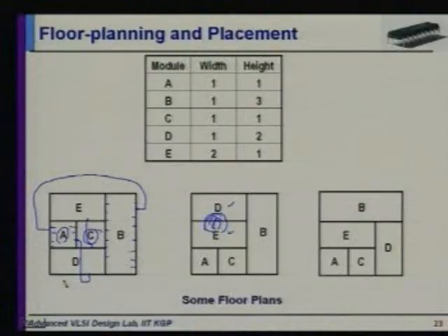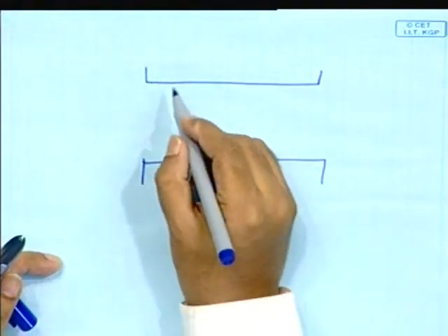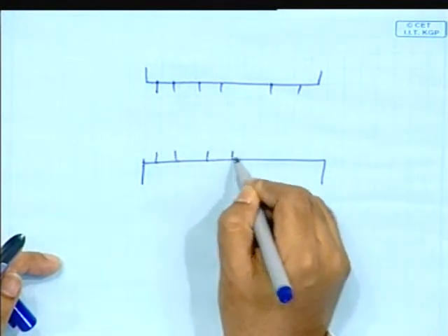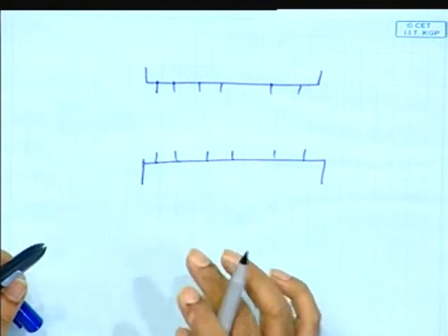After you have done floor planning, then you have to do the routing, the actual routing of that. Now there are various ways in which people do routing. There are, for example, matrix based routing algorithms. So you say that, okay, I am going to have the chip, these are two modules, this one has these pins, this one has these pins, and I am going to do routing with only two layers.